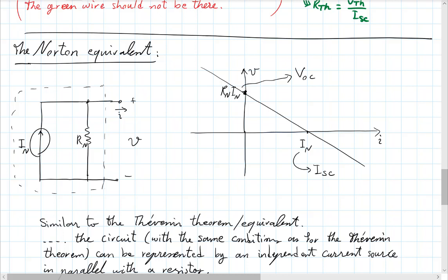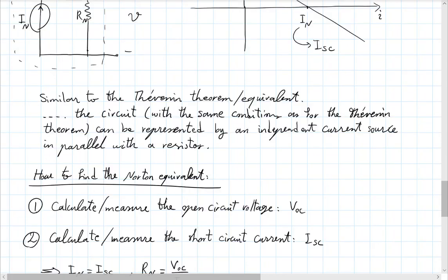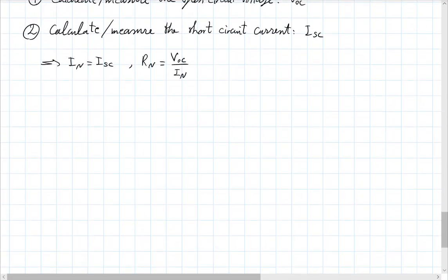Okay. So it's really just a change of names if you think about it from an abstract point of view, right? And remember the whole notion of equivalent circuits means that sitting on the outside looking at those 2 points, you have no way to tell if inside there is a resistor in parallel with a current source, a resistor in series with a voltage source, or a big circuit with many resistors and dependent sources and independent sources, assuming everything is linear, right? So this is equivalence, and it's a very powerful concept. And here's an immediate thing. You can very quickly and easily switch between a Thevenin and a Norton representation.